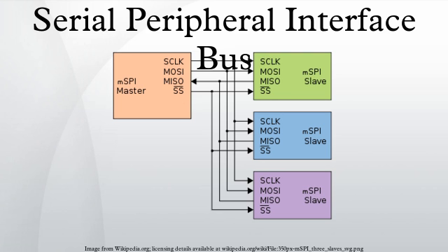Related terms, intelligent SPI controllers: the queued serial peripheral interface is one type of SPI controller, not another bus type. It uses a data queue with programmable queue pointers allowing some data transfers without CPU intervention. It also has a wraparound mode allowing continuous transfers to and from the queue with no CPU intervention. Consequently, the peripherals appear to the CPU as memory-mapped parallel devices. This feature is useful in applications such as control of an AD converter.